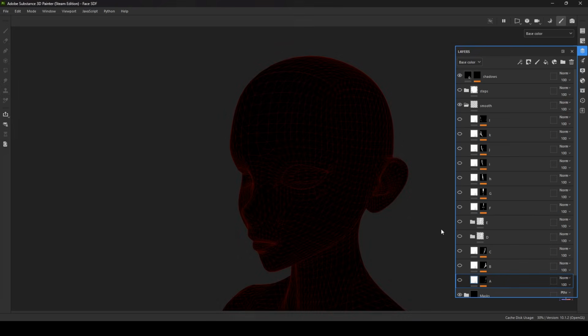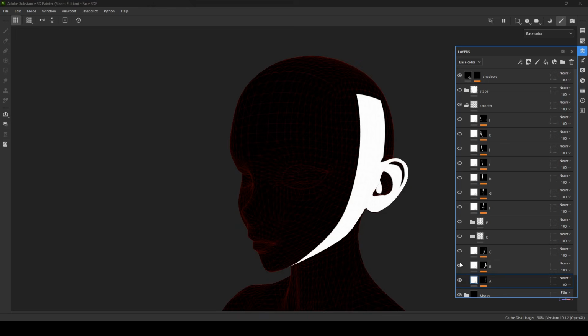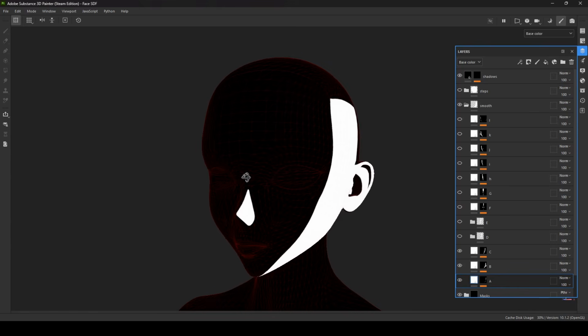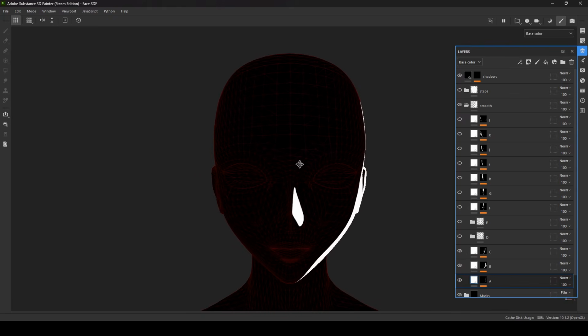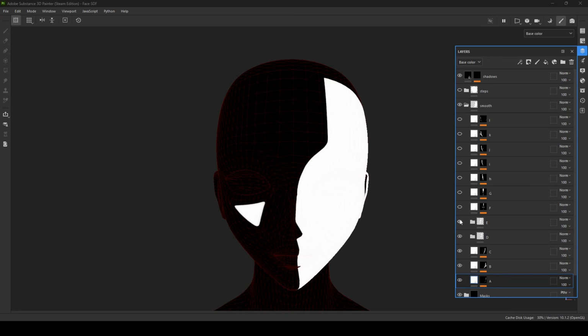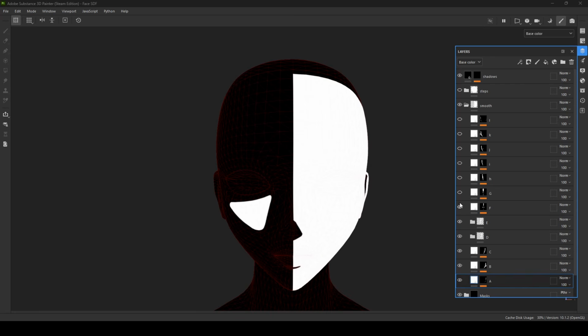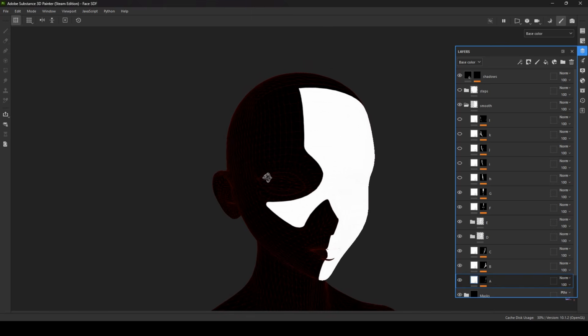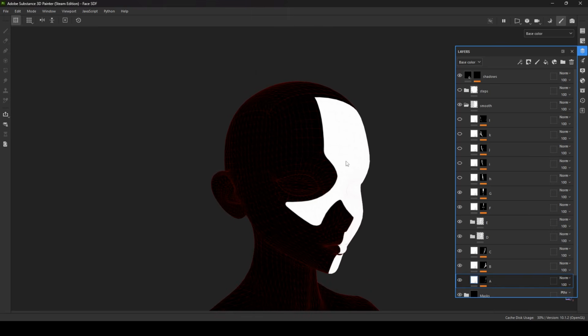The first step consists of creating a series of textures that represent how light affects your character's face as it turns. In my case, the lighting progresses from the left side of the face to the right. These lighting steps should be painted similarly to how you would usually edit normals for anime characters. If your goal is to achieve smooth lighting transitions, painting more steps will give you more precise and natural results. In my setup, I created 12 lighting steps.